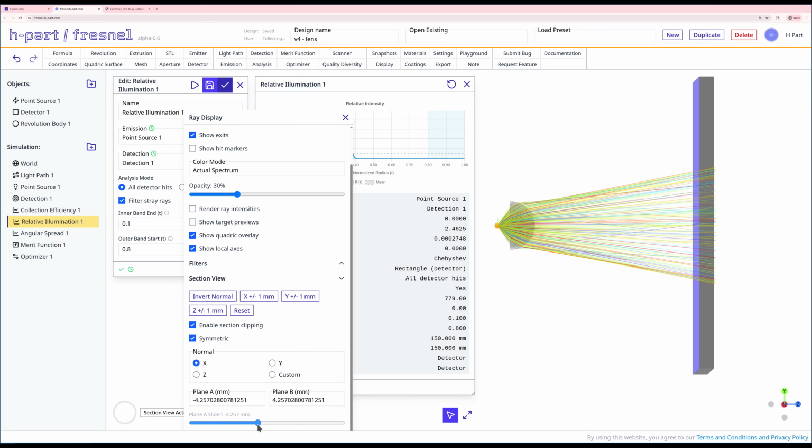Okay, I'm going to start to pull it out, and we're going to see more rays traveling through the system. And if we pay attention, we can see what's creating this peak. I'm going to pull it back. Did you see it? Okay. So now we're right about where our original section view is. And what you notice is the light that is coming out on a quote-unquote normal trajectory is going through the lens, and it's heading somewhere around here, in this area where our peak is. And just based on these rays, there shouldn't be a peak, because there's nothing here that's creating a bunch of different rays from different angles out of the LED to hit in one spot, and that's about the only thing that would create a peak.